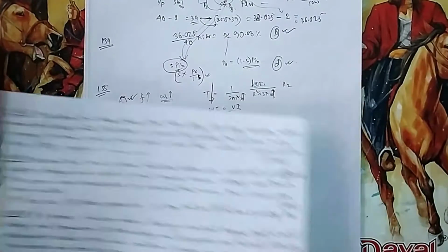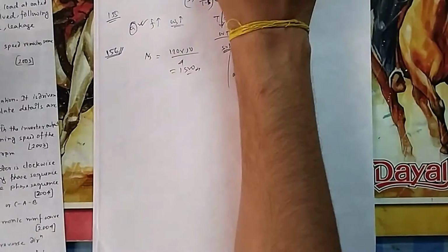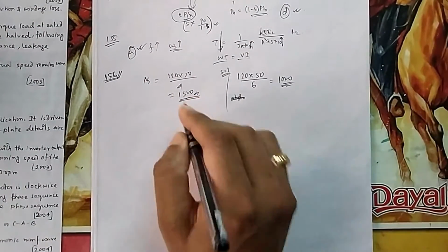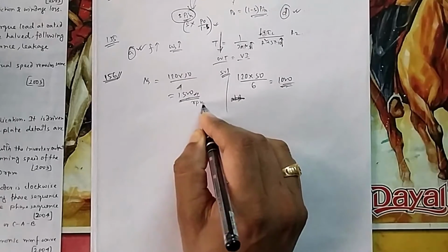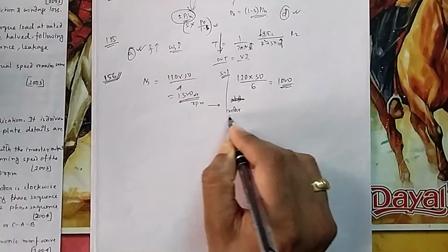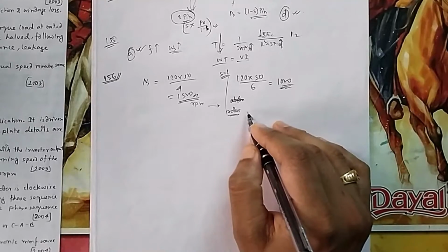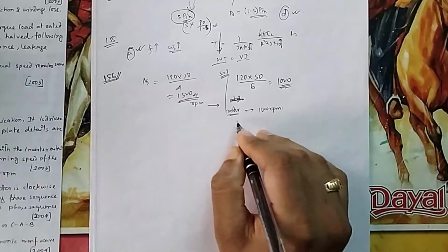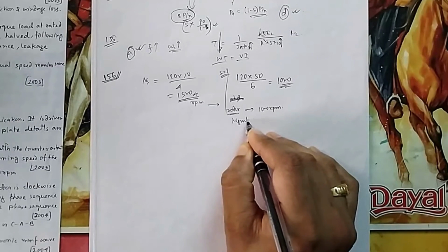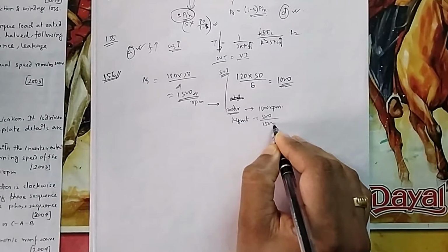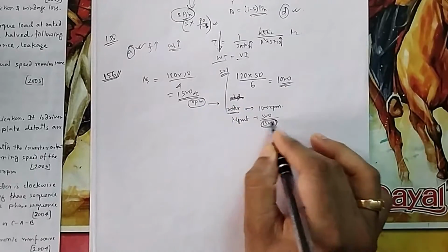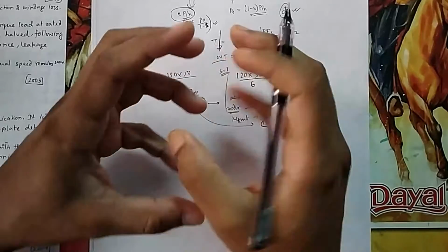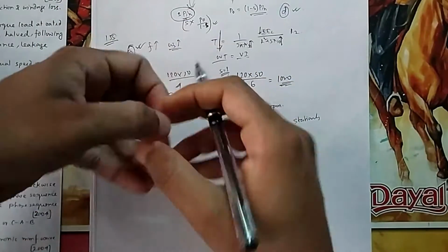So actually what happens in a synchronous machine, both these rotating magnetic fields are running at the same speed. Suppose your stator magnetic field is running at 1500 rpm. In case of the rotor, the rotor itself rotates and its magnetic field also rotates. Suppose the rotor itself rotates at 1000 rpm and then its magnetic field will also rotate plus 500, so total rotation will be 1500. So ultimately the rotor magnetic field and stator magnetic field will look stationary to each other. They will get locked.